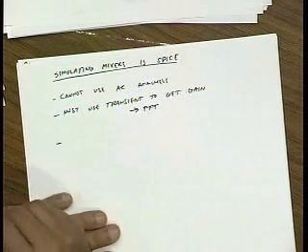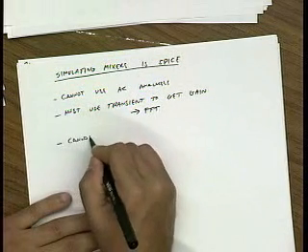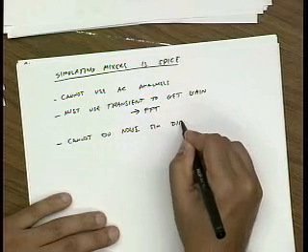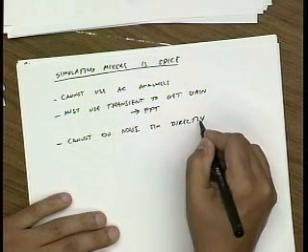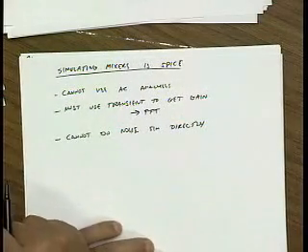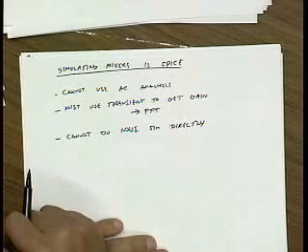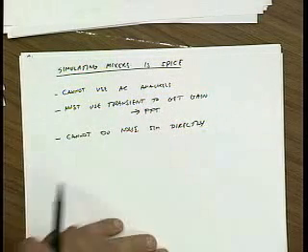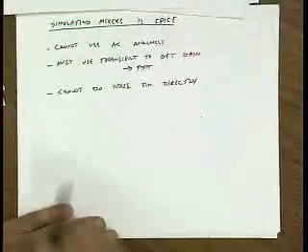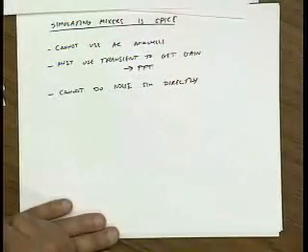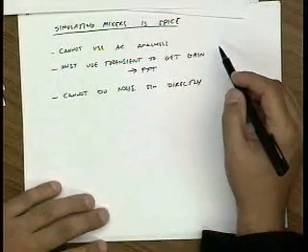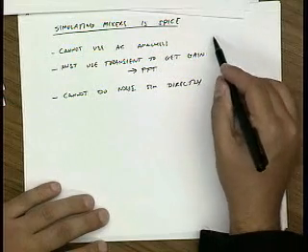The other thing that's a bummer is you can't get noise. You can't do a noise simulation directly. And when I say directly, the indirect method is a PhD thesis. And I'm actually serious. Somebody wrote their PhD thesis at Berkeley on simulating the noise in mixers using SPICE. Okay? So it's not something you want to do on a nice Sunday afternoon. Okay, so we can't do noise, that's a problem. What's wrong with this transient?